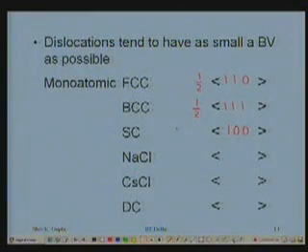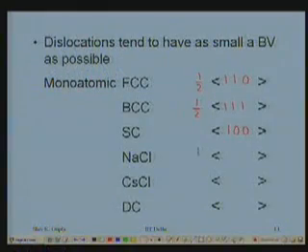Now you shall see the other three which I am showing. It is the displacement from one lattice point to the next which gives me the stable displacement for a dislocation line, or the Burgers vector of the dislocation line. The sodium chloride would be again like in the FCC, half 1 1 0.